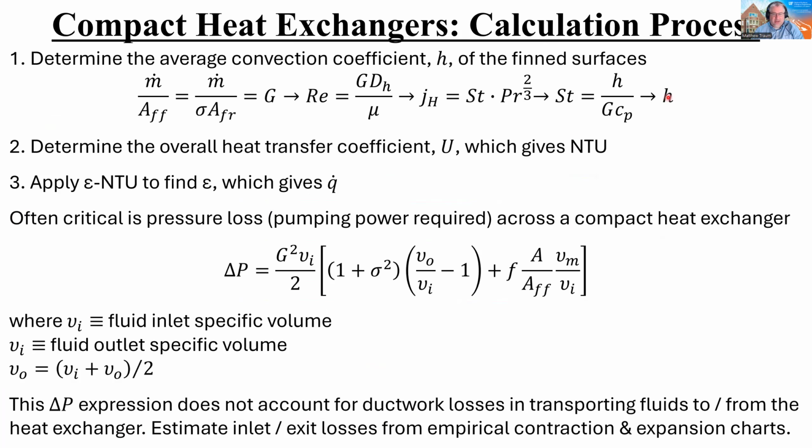So typically you just take the h value for the hot side, the h value for the cold side, add them together. That's typically your U value, right? There's very little other resistance to heat transfer because everything else internally is metal and very thin. So small resistances to heat transfer through conduction.